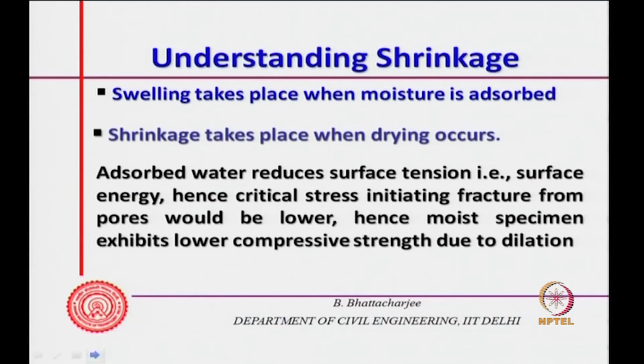Since the surface energy becomes low, if you recollect when we were talking of strength, critical stress is a function of the square root of E gamma divided by pi into half of the crack width, or pi r. Now, surface energy is reducing when the specimen becomes moist, and therefore critical stress reduces. Therefore, the moist specimen exhibits lower compressive strength due to this dilation effect. So, this is going back to our situation.